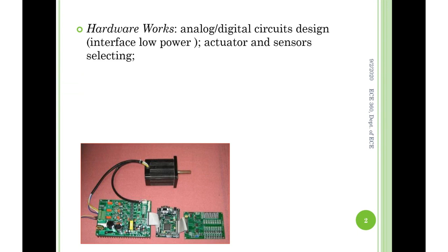You need to separate the high power circuit side and the low power control side in the same PCB board. That's possible, doable, however, more complicated. In my experience, I always separate them. I purchased a control board from a semiconductor company and designed the power board myself.